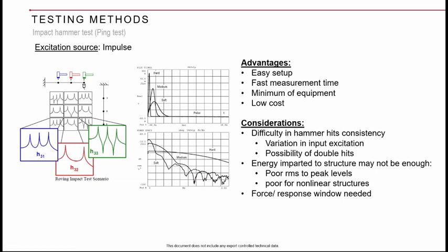For example, you take a tube with certain clamps, loop clamp, P clamp, or block clamp, and you have strap clamps on the tubing systems. When you just go and do an impact hammer test, the energy imparted to the system will be less. Therefore, the mode shape required to overcome this kind of frictional clamping force will not be excited, and you will see that all the clamps are quite stiff or are actually giving you a bonded contact kind of scenario, fixed joints.